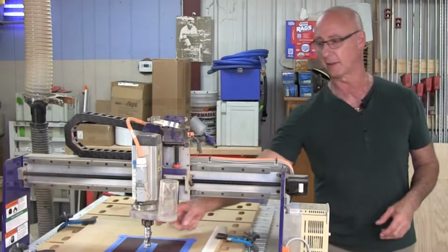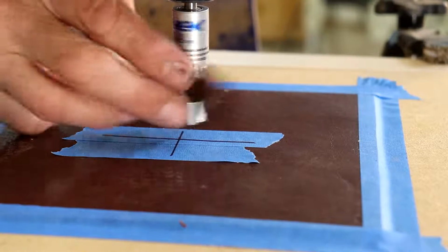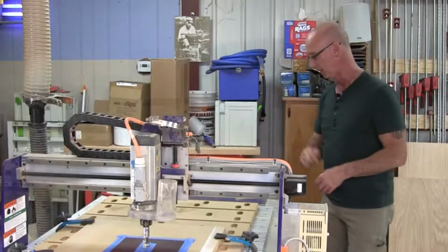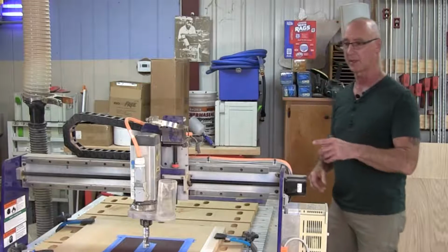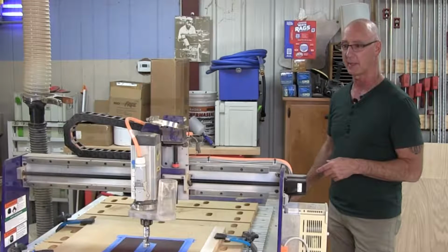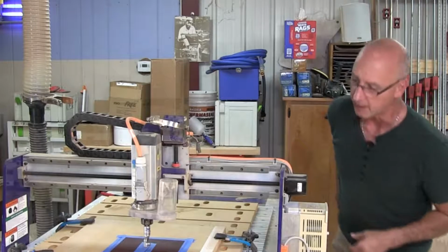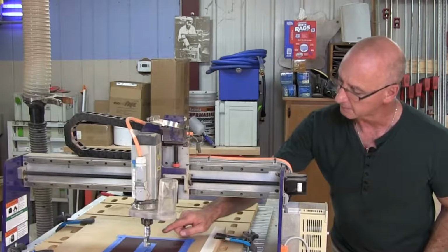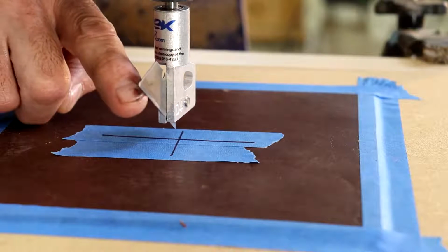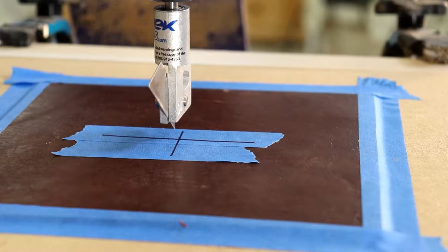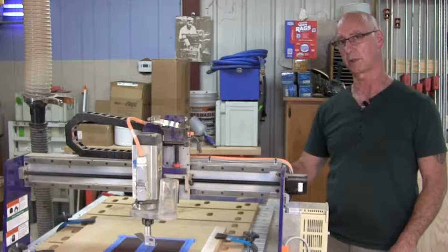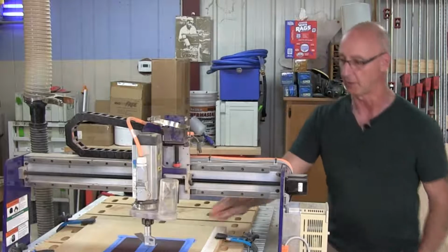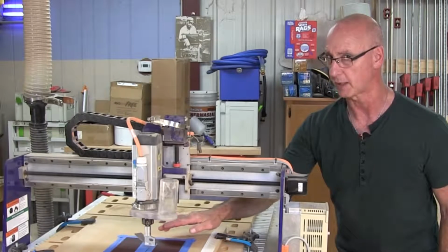The other thing that's weird here is that because of the offset in that drag knife, we can't just put the point over the XY center like you would if it was a V-bit. So here's what I'm going to do. I'm going to use my laptop here to manipulate the gantry and get that point over the center. But now, if I turn it, we're no longer centered. So I take a little bit different approach to the drag knife than I do with my regular cutting tools. What I'm going to do is turn it in the direction in which I am centering.